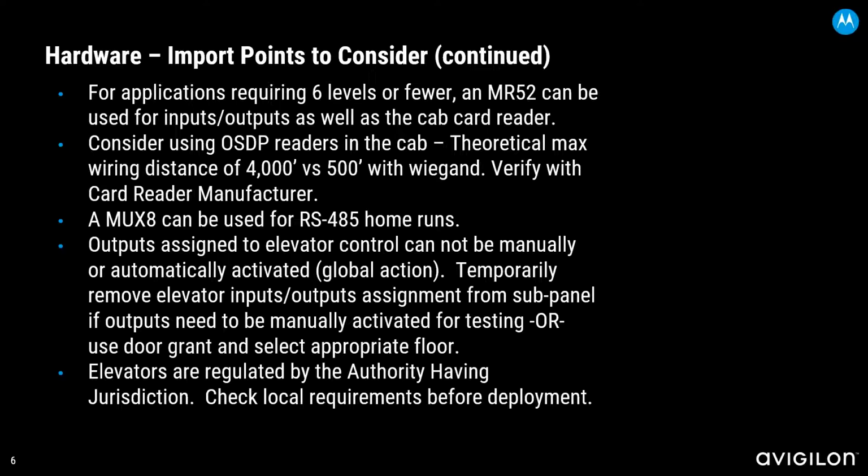Now, that's less hardware in the cab, less things that you have to have the elevator control company do inside the cab. So definitely consider that. Theoretical max distance of 4,000 feet. However, check with the card reader manufacturer, to make sure that you can in fact get the distance that you need to get.